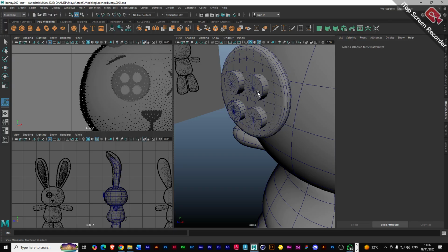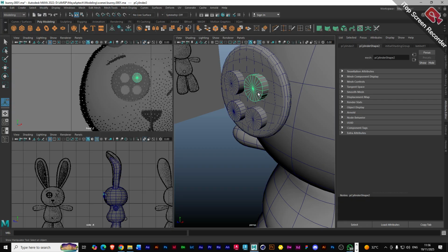You can actually do it one by one, it's just that it might be stressful if you have more than four objects. Maybe you have 20 objects that want to cut through a shape. One of the easy things to do first is to combine the cutting objects to become one object, so that the software sees them as one object.